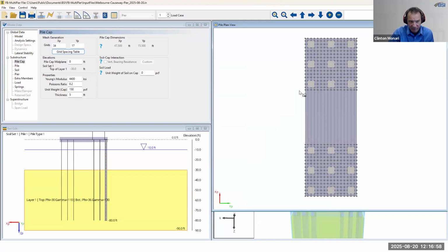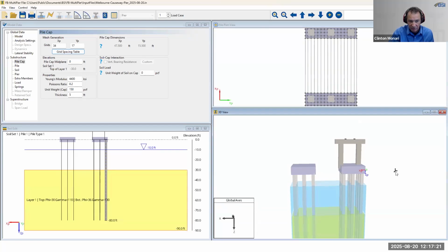And then I'm going to hold down the left button of the mouse, and I'm going to drag a box over the shell elements that we want to get rid of. Okay. And then I release the left button of the mouse. And that removed those shell elements. So now if we take a look at our model here, that's what we want there. We want water in between the 2 parts of the pile cap. So that was another major change. We'll go ahead and save the model.